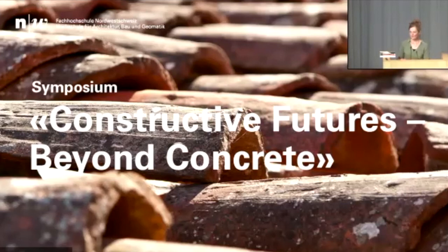I think you do more things in the beginning that you otherwise do later, right? Like in the beginning, it's much sooner than usual. You have to understand the materials, especially when you work with the structure. Let's say you have the steel structure, like we saw before. That's the core of the building. So very early in the process, you need to understand what that means, because this has an impact on your building height, the whole shape of your building and how you approach it. And then that is basically done early and informs your next steps.